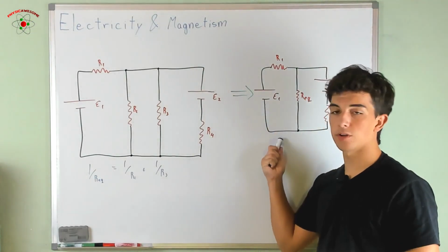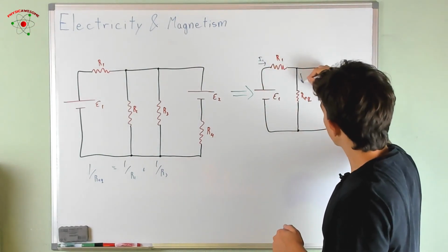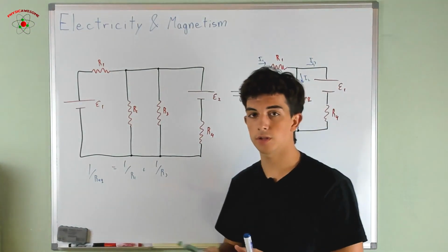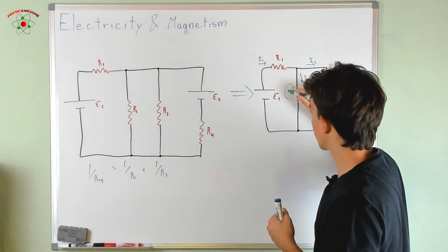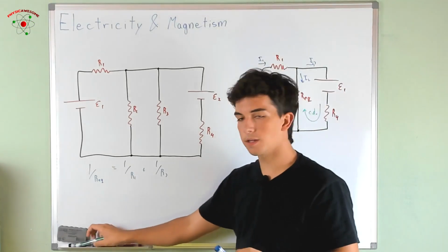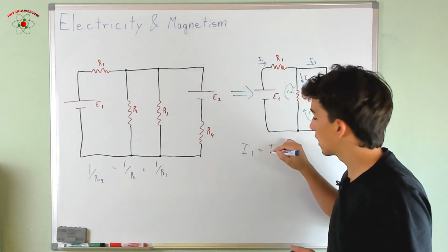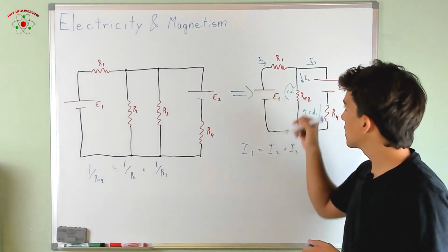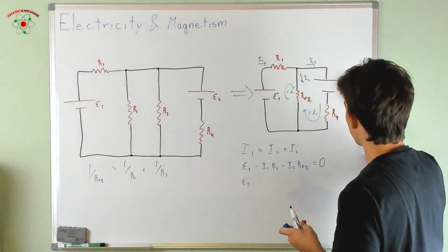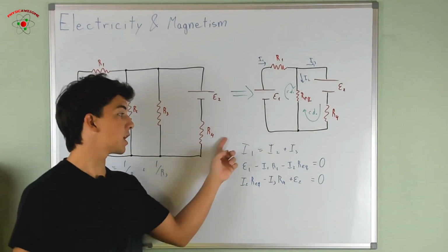We would get this circuit, and by establishing the currents, which is pretty easy, have I1, I2, I3, and also the current directions, the circulation directions, sorry, in this and these directions, we find simple equations, first applying the first Kirchhoff law, I1 equals I2 plus I3, and then applying the second Kirchhoff law, and we find our system of 3 equations, which is much more solvable.